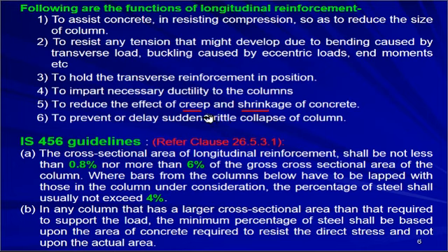Now what are creep and shrinkage? Both mean the same thing, that is, a reduction in volume of the concrete, but the reasons are different. Shrinkage is because of loss of moisture and creep is because of sustained loading. Both actions are inelastic. So you can reduce the effect of creep and shrinkage by adding reinforcement to prevent or delay the sudden brittle collapse of the column.